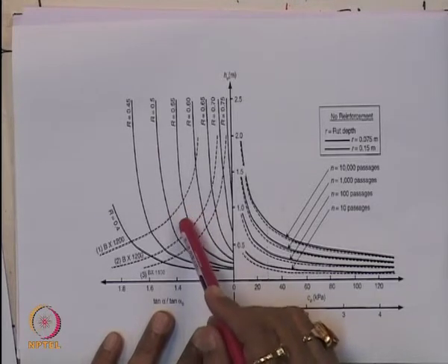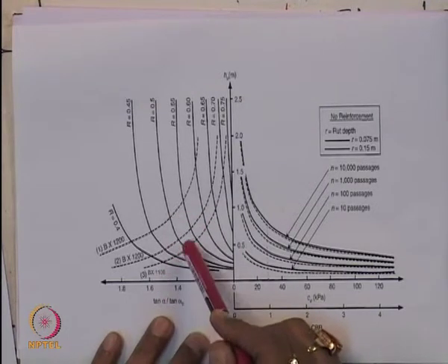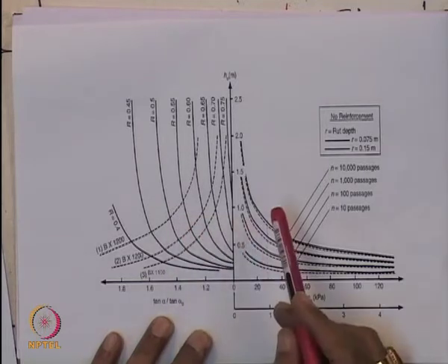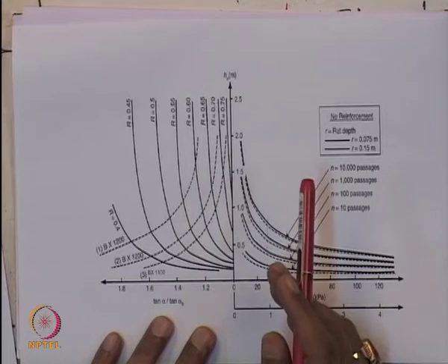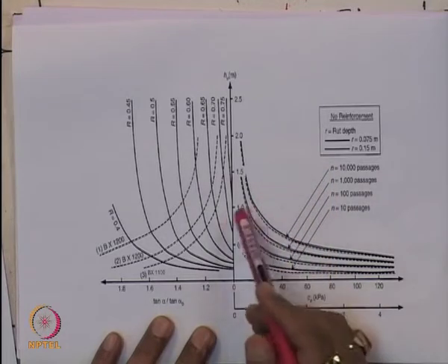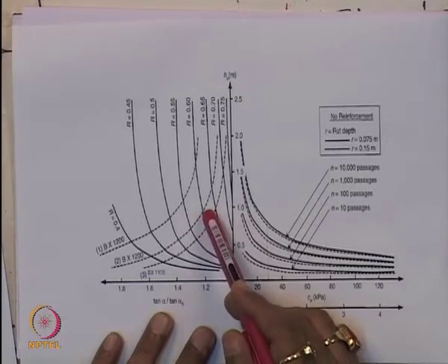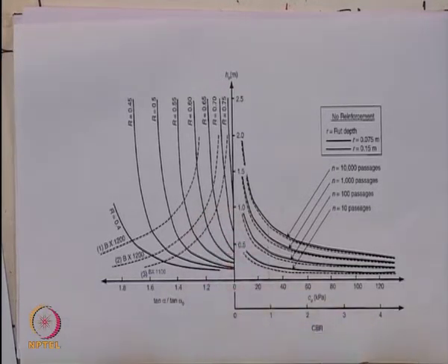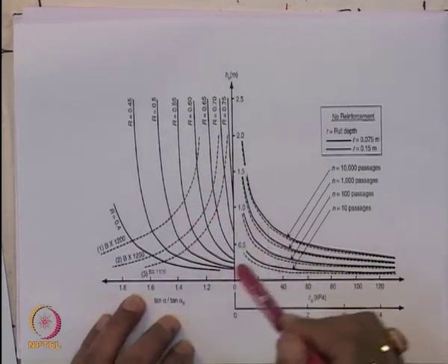So this is the kind of very soft or compressible foundation soil for unpaved aggregate. And you know the mechanism of reinforcement: increasing the soil strength, enhancing the load spreading, and membrane support by controlling the rutting.